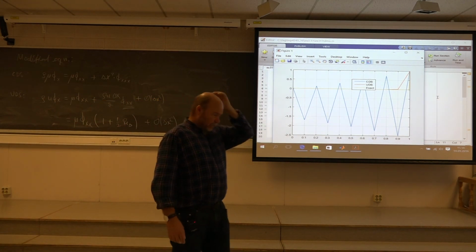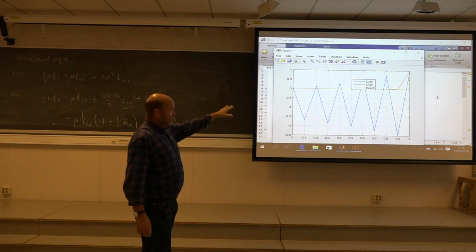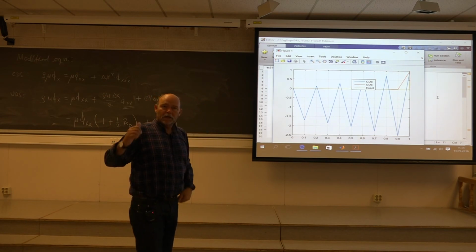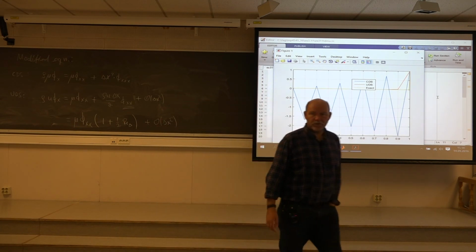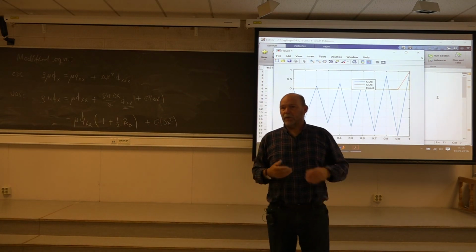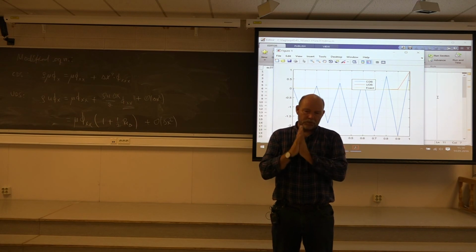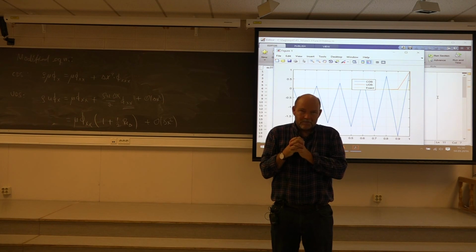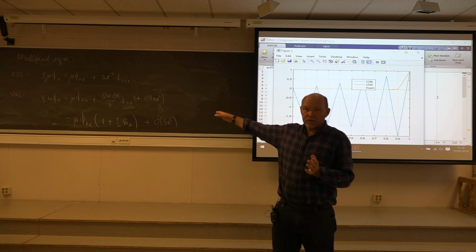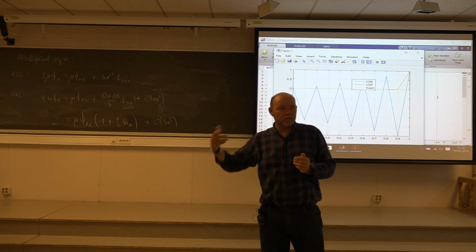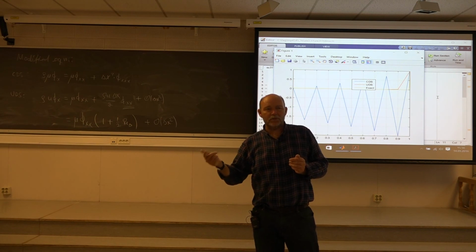So why do I stress so much about this? Well, first of all, you should know it's a bad idea. Second, we're going to use it anyway. A lot of code still uses it. And we are also going to use it, but we are going to use it with care. To get a solution here, let's start with the first order upwind scheme. It's very stable, unconditionally stable, very easy to get a solution, but we know the solution is stupid.